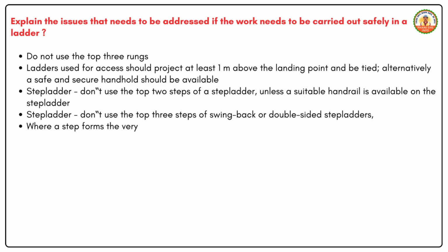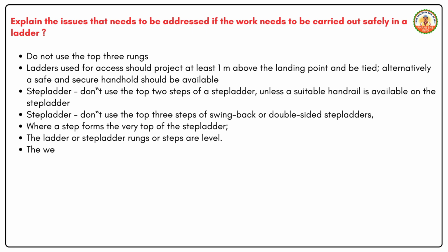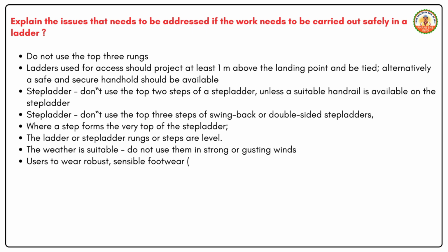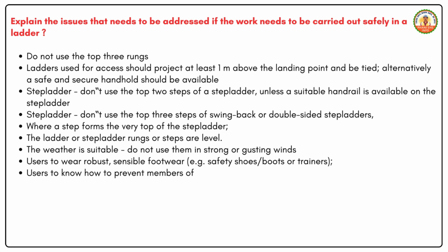where a step forms the very top of the stepladder. The ladder or stepladder rungs or steps are level. The weather is suitable. Do not use them in strong or gusting winds. Users to wear robust, sensible footwear, e.g. safety shoes, boots or trainers. Users to know how to prevent members of the public and other workers from using them. Users are fit.